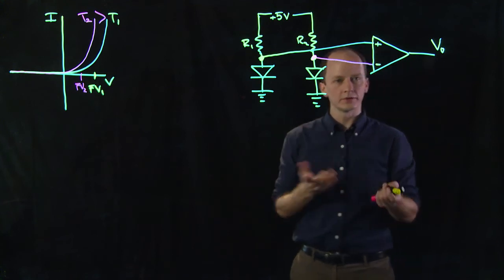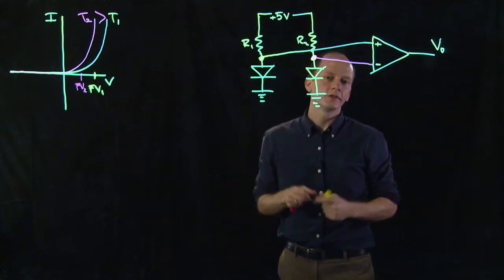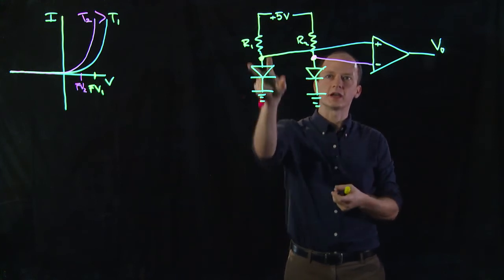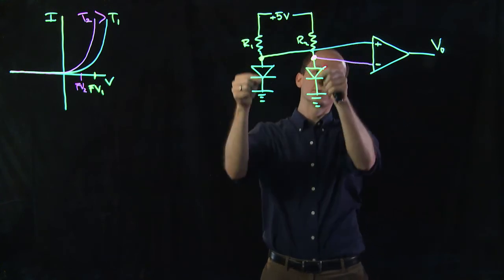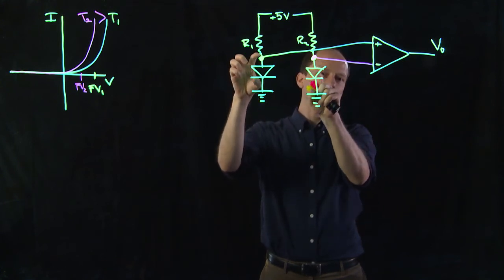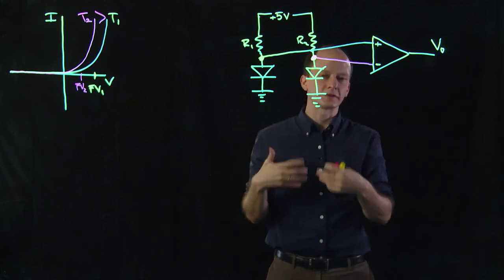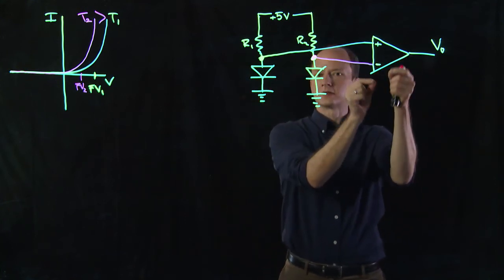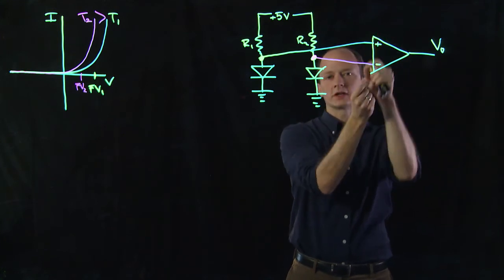Okay? So one little note here, though, right? You saw in previous weeks, these resistors, even if you choose them as being the same, there's a tolerance to the value of the resistor that you see. There's some slop, right? Plus or minus 5% in the actual resistor values. That difference in resistors is going to cause a difference in currents that flow through these, right? That difference of currents might cause a small change of the forward voltages. So even if these are experiencing the same temperature by sitting in the room, there might be a small difference of the voltages here. Moreover, something we haven't talked about with the op-amps, but the two inputs can be sitting at slightly different voltages, even with nothing connected to them.